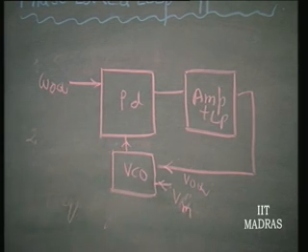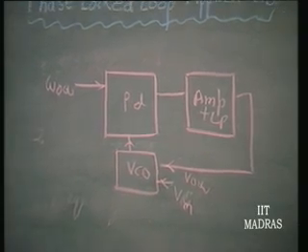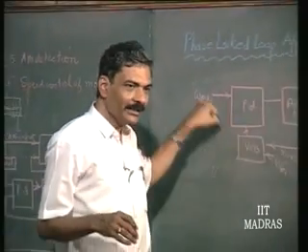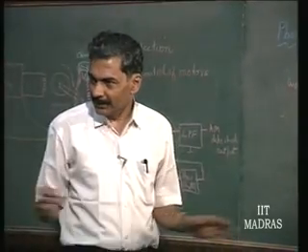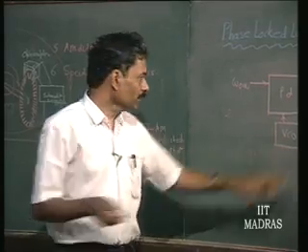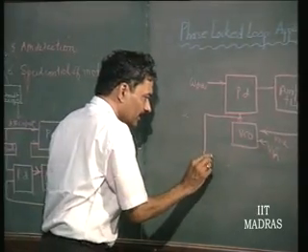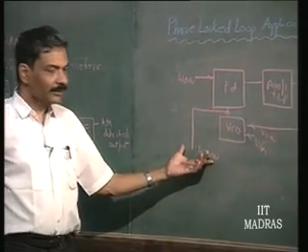Now, when Vm comes into picture, you are tuning the VCO to a different frequency compared to omega naught q. Okay. So, automatically the phase shift should change, frequency will remain the same. Okay. Now, the phase can be changed linearly by changing Vm. Okay. So, the output can be taken here, this will correspond to omega naught q, but okay, it is phase modulated.